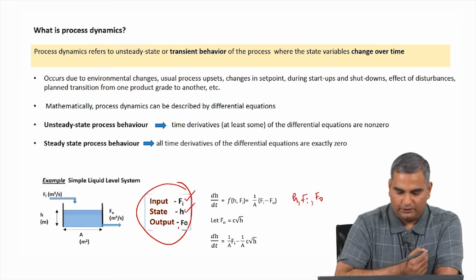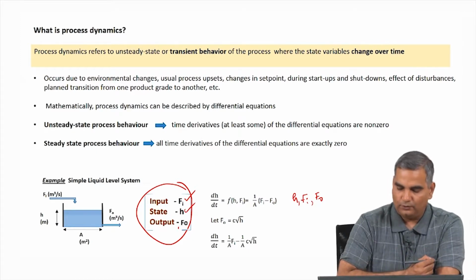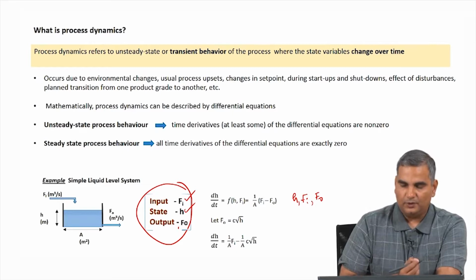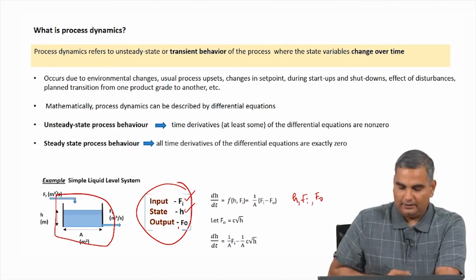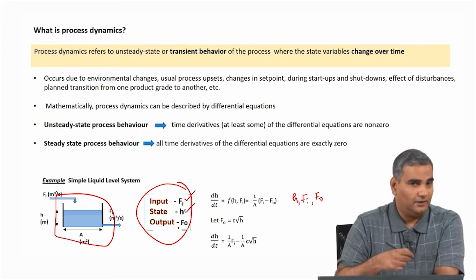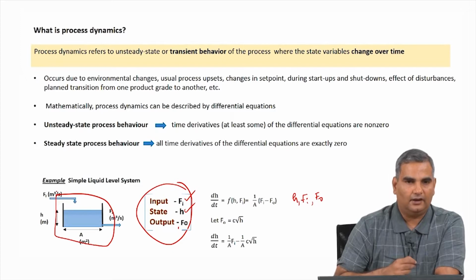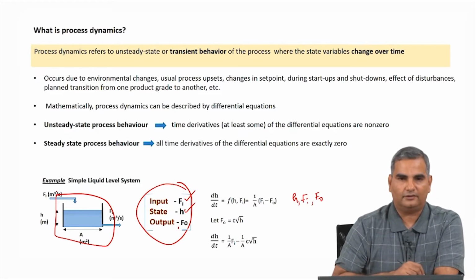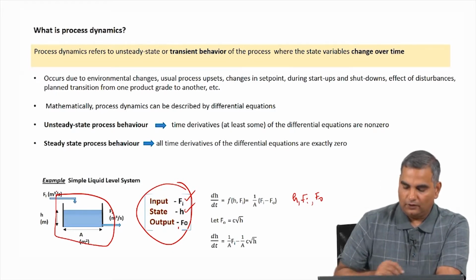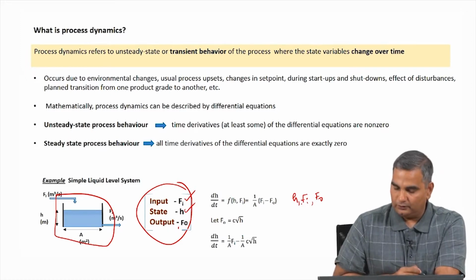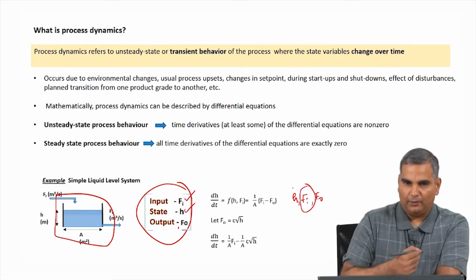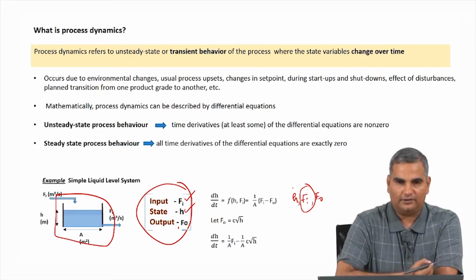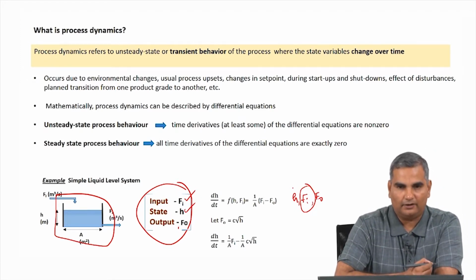If you think about this a little more carefully, you will notice that since we are writing the equation for the tank, and remember I drew a battery limit something like this, the system equations themselves cannot define Fi. So, Fi has to come from outside. What you need to realize is that this Fi comes from outside, so we do not have to count this as a variable for which we need to write a model equation.